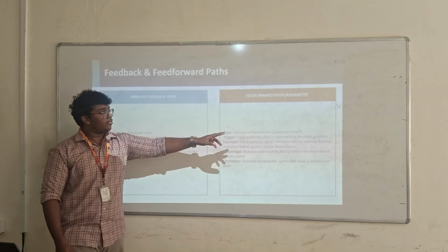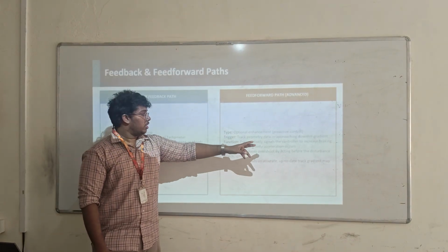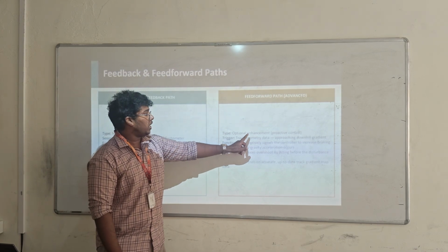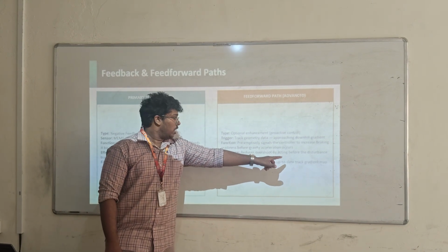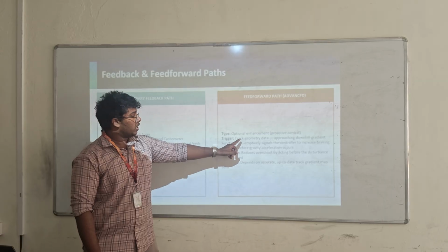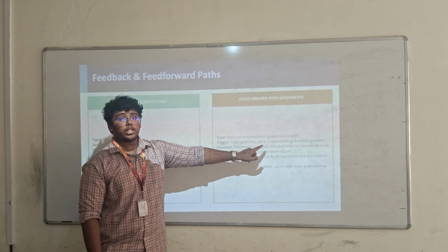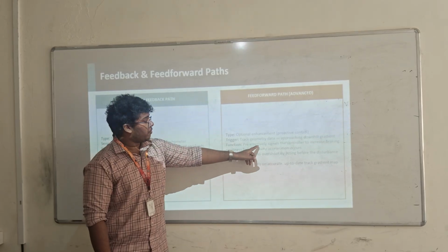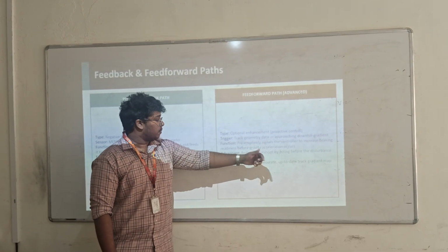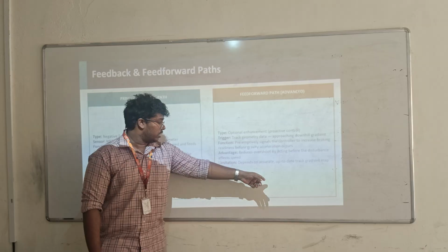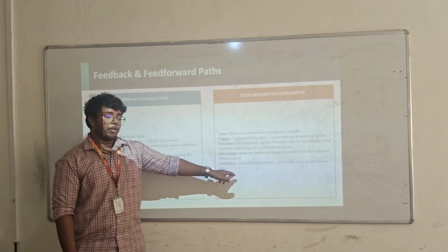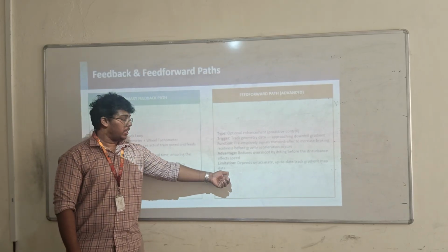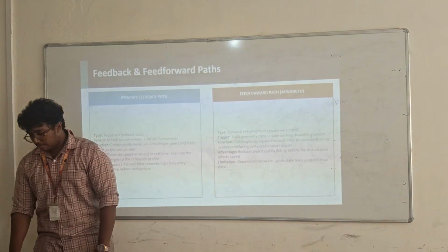Next, the feed forward part, which is an optional enhancement and is proactive control. Here the trigger is track geometry data showing an approaching downhill gradient. Next, function: it pre-amplifies the signal to the controller to increase braking readiness before gravity acceleration occurs. The limitation is that it depends upon an accurate, up-to-date track gradient map and other conditions.